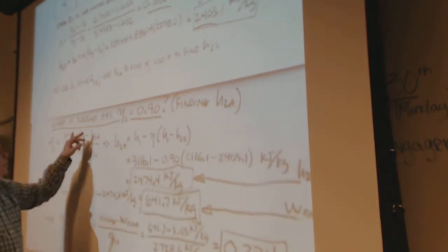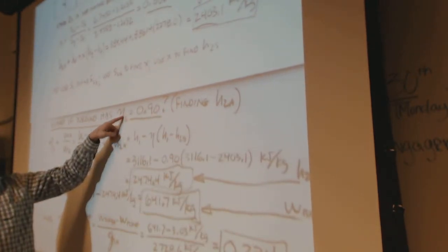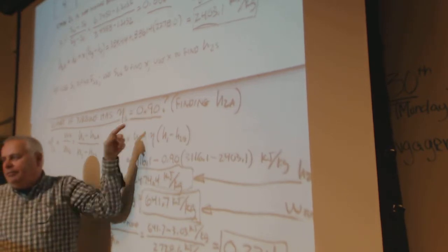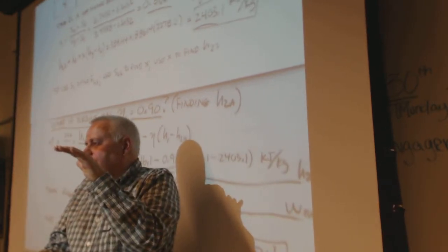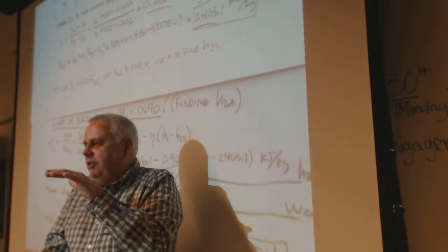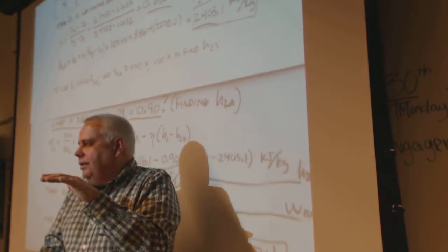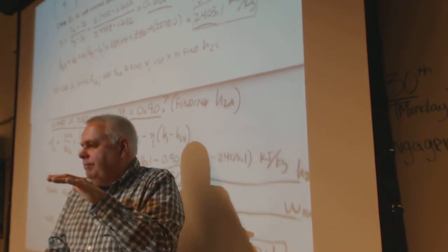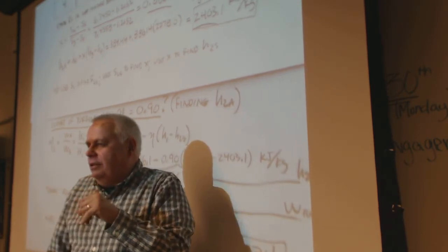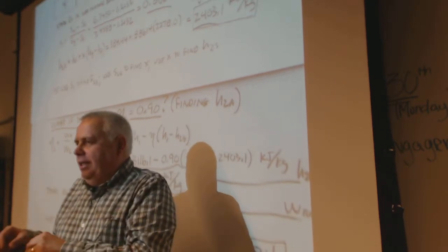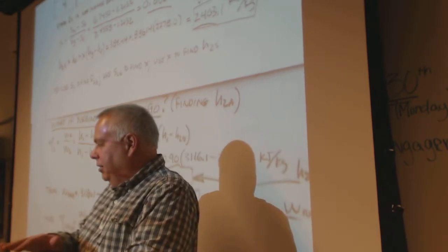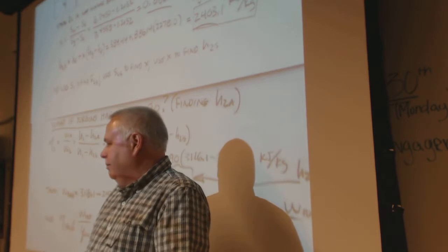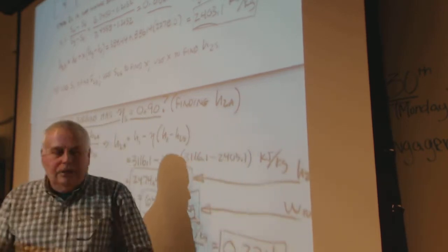So, actual output, what if it wasn't a perfect turbine? What if it had an isentropic efficiency of 90%? That means that number I just got said that's the floor, that's the most energy it can possibly convert for thermodynamic reasons. That's what entropy is all about. Energy below that can't be converted. It's like the water that comes out of a dam goes down to the river. The river's at a 400-foot elevation, but that doesn't help because the river's there and you can't get more elevation out of it than tailwater rivers. There's a limit.